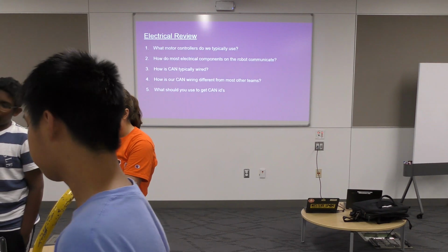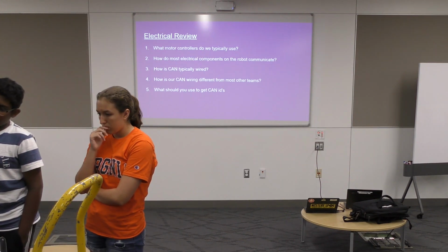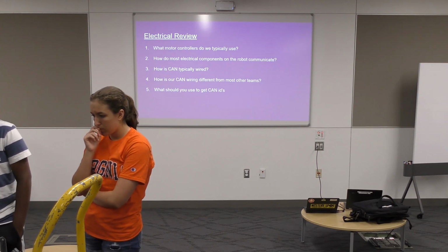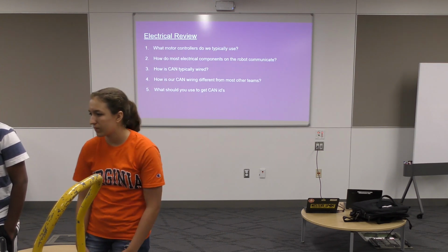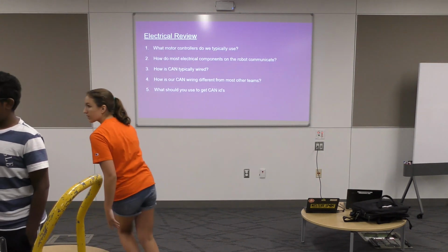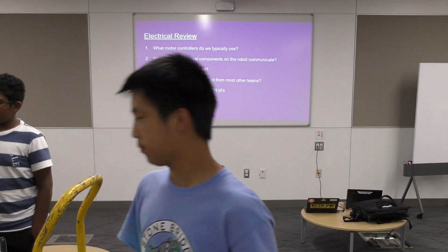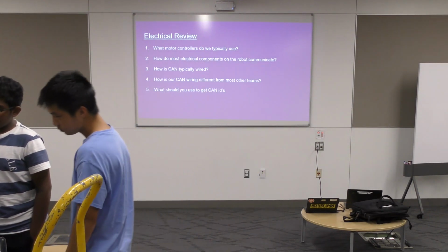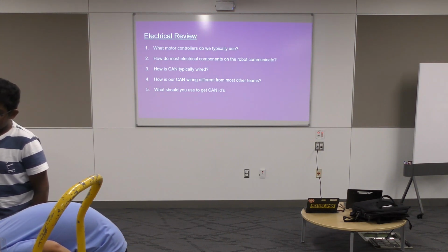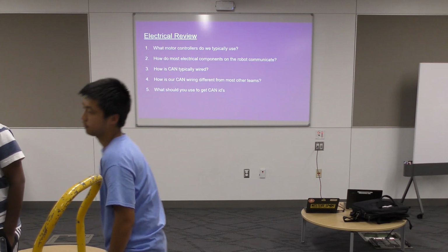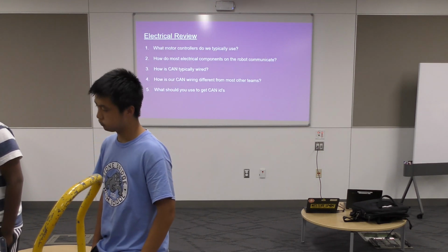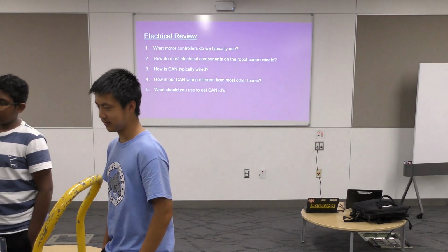And these green and yellow wires here, that's the CAN. So normally, let's take this Talon because it's easy to see. You have this pair of wires, and then you have this pair of wires, right? You have 2 pairs of wires. They're both CAN. So there's 2 pairs of CAN wires going out from one Talon. Normally what you do is you take this wire and connect it to the other pair from this side. But what we did instead is we terminated one side, wrapped it in electric tape so it doesn't go anywhere, and took the other one and connected it to this hub over here.